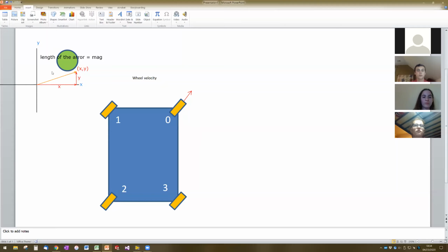So we still have this joystick here in this orientation, so we want to translate this way, but we also wanted to, let's say, rotate counterclockwise. I'm going to go ahead and make some more arrows here just so we have them. Does anyone want to just think about it? There's multiple solutions, you're not going to get an exact thing. Then we want to think about what the wheel orientations might need to look like physically in order to both translate in this direction and also rotate in the counterclockwise direction.